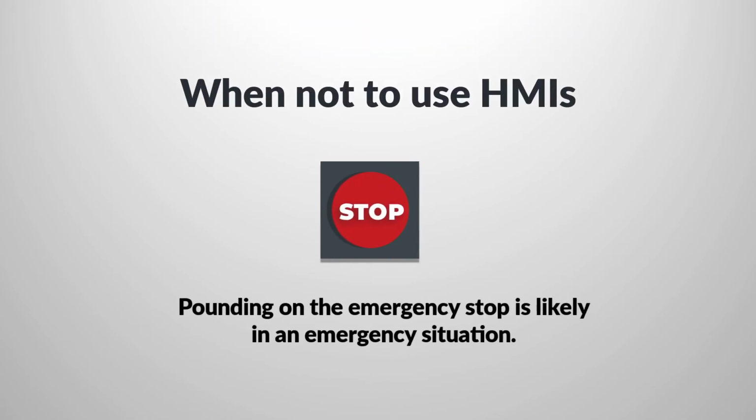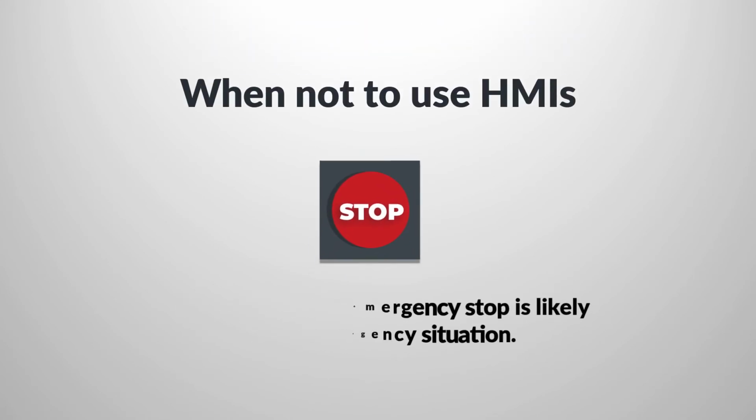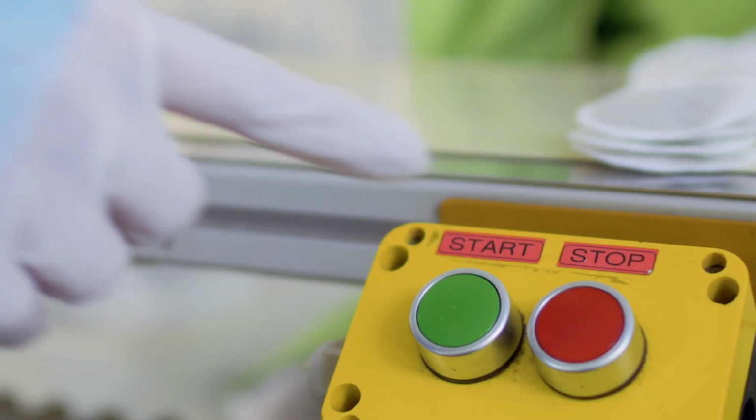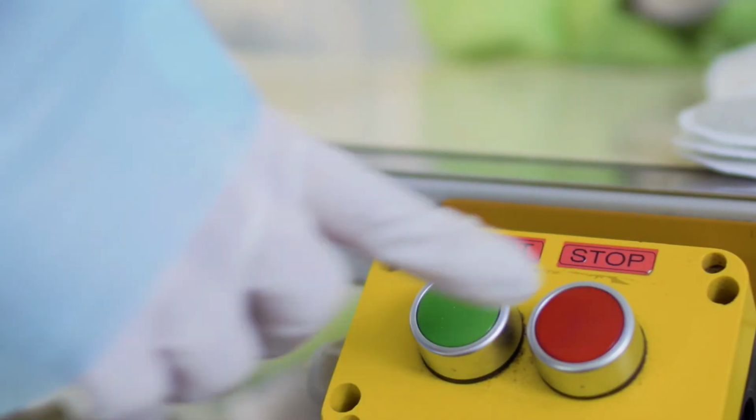Pounding on the emergency stop is likely in an emergency situation. It cannot be a button on the HMI screen. Safety standards require it to be a hardwired push button.